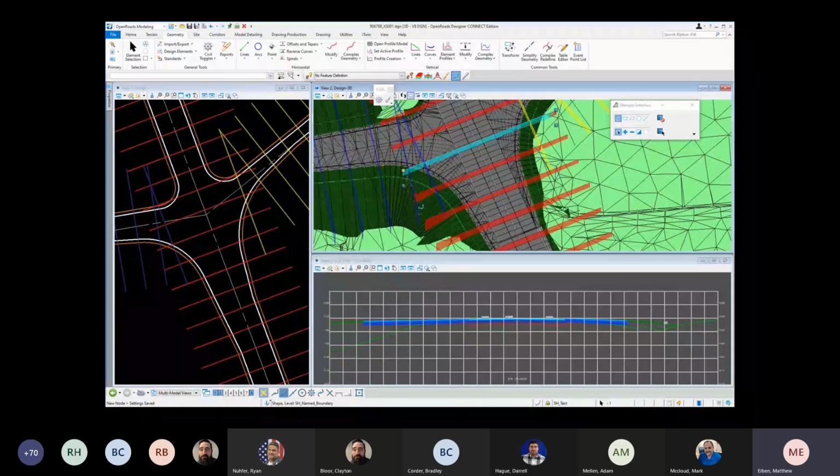Now, because they're in a 3D view, I'm really not going to advise modifying these graphically, especially in this way without that angle being preserved. You're not exactly sure where you're going to be clicking. It may look like you're data pointing out there and getting the right station or snapping to an element, but it may be off a little bit, or it may even be the wrong elevation. And you're probably not going to get what you want here. If you wanted to do it graphically, I would definitely recommend preserving that lock, and perhaps you could snap to the other name boundary you wanted to intersect.